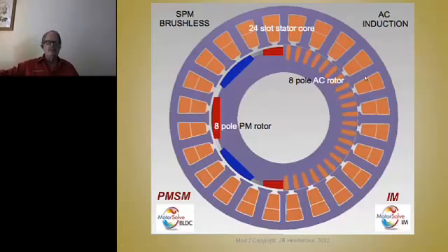Remember I told you how the stator field rotates at 60 hertz or whatever frequency, but the rotor has to slip. It has to rotate less than that. So if these 4 bars are creating a north pole, and this rotor is going slower than its synchronous speed, then I've got to drop a bar and add a bar as this rotates.